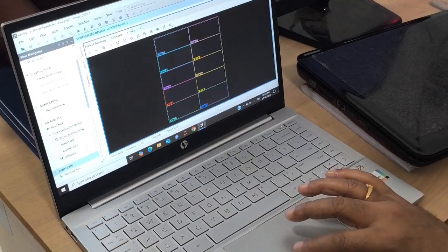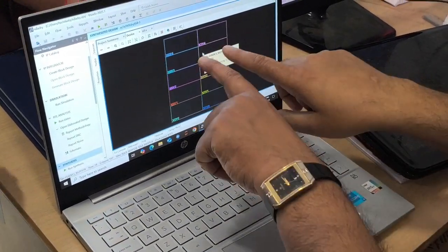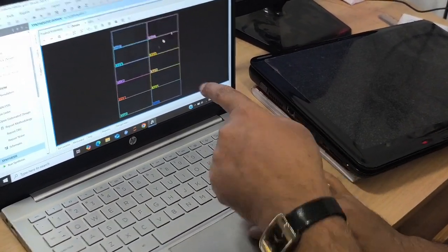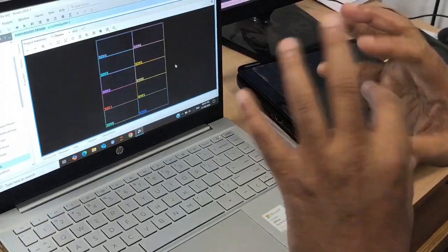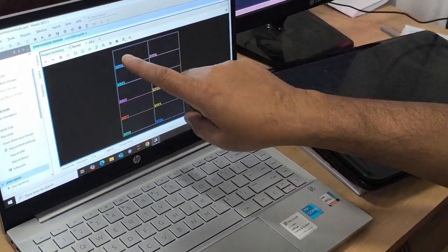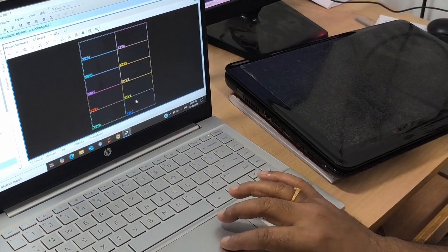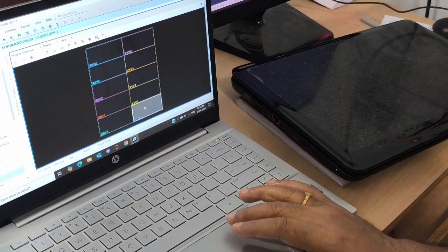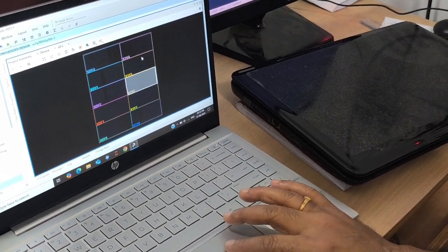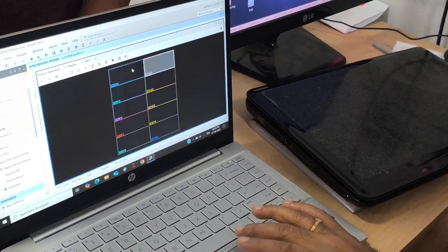Here it is a chip. It is a floor plan. I told you that in ASIC you have to make this by hand in the ASIC flow, but here it is the FPGA flow. The algorithm is automatic; the Xilinx software is automatically doing this and creating this floor plan. Under this floor plan, where your code is, you have to double click it. Here it is not there. You cannot find any wires here, because the design is very small, and this FPGA